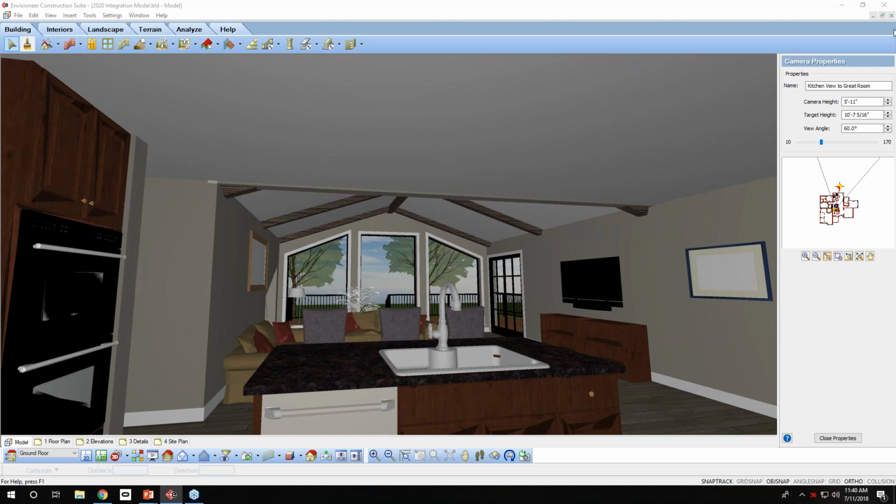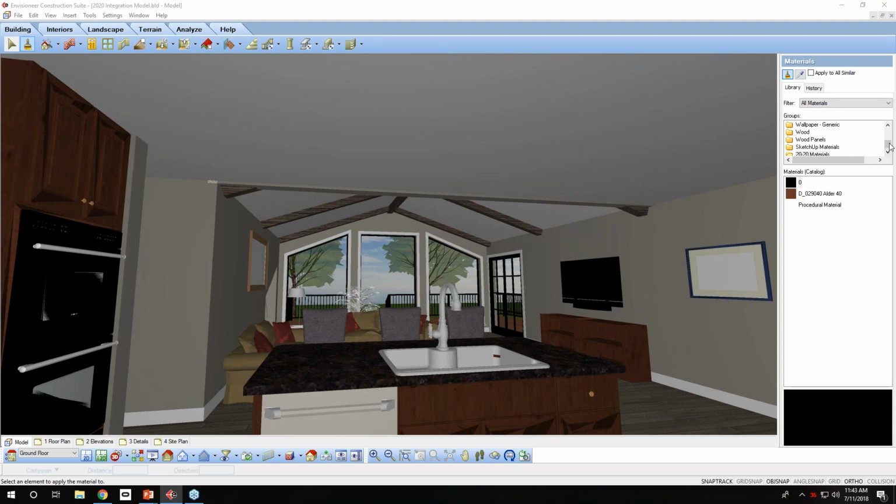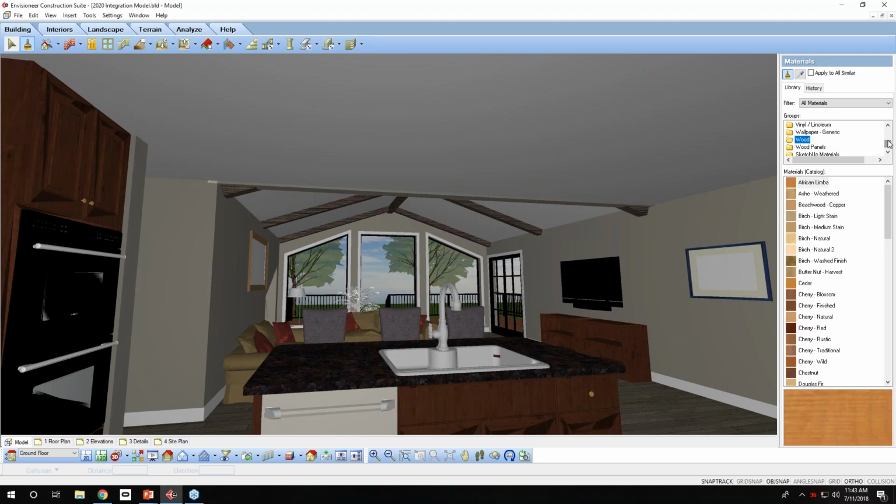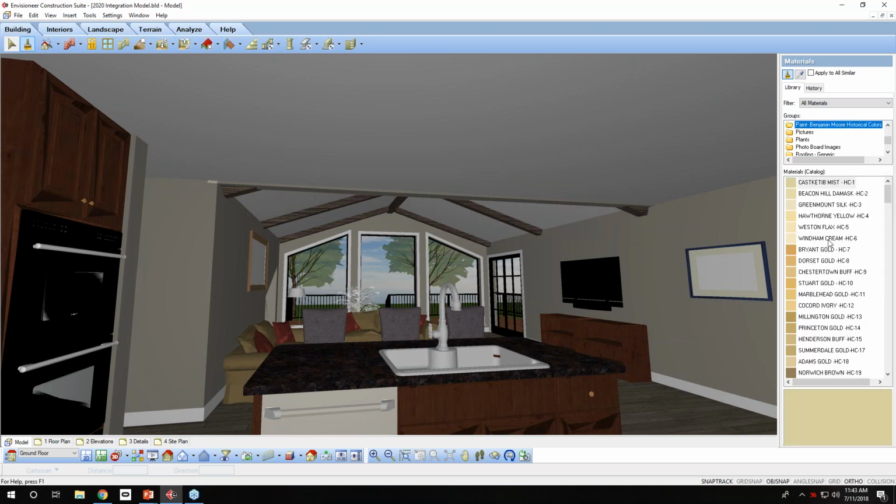Remember, you can take advantage of the material paintbrush in Envisioneer, grab the paint color that you want, and add it to that as well. So don't feel like once you're locked into one, you have to do all these import exports. It's quite flexible. That will allow more rooms to go out, and once they're in, we can take advantage of painting it here as well.